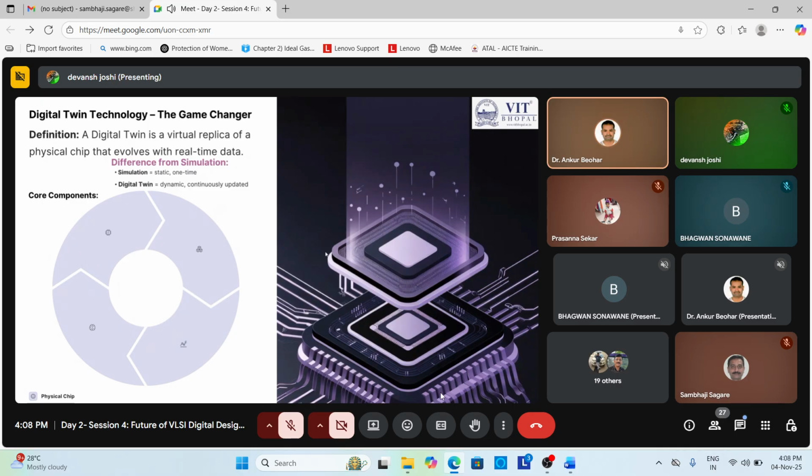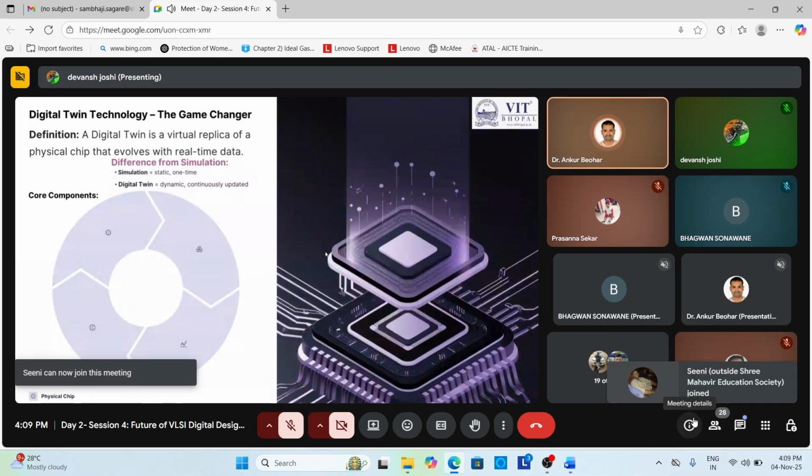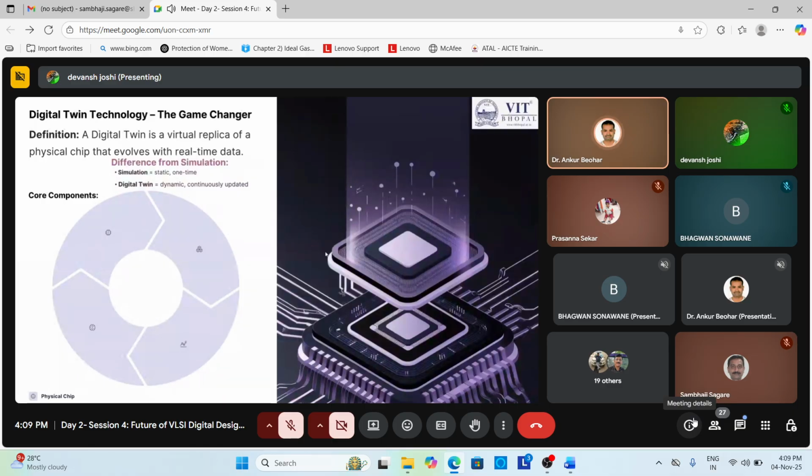Then we have placement. Place the standard cells such as gates, flip-flops, etc. inside the assigned areas, the specific chip area that is significant for the placement after the floor planning, where we minimize the wire length and delay. Now in continuation we will have clock tree synthesis, where we distribute the clock signal evenly to all flip-flops with minimum skew values, giving balanced clock distribution for synchronous operation. Then we will go for the routing, where it connects all the placed cells using metallic interconnects.